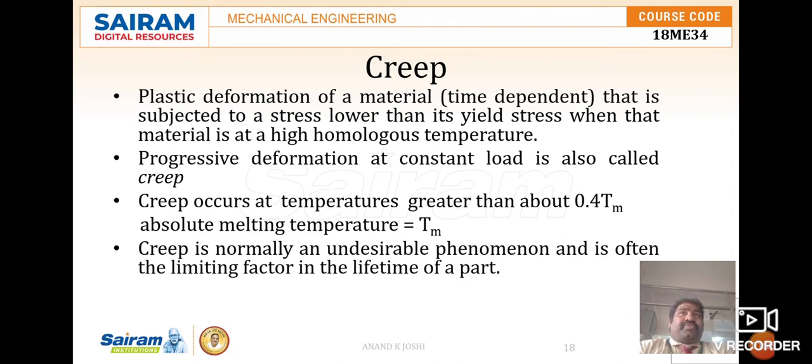Creep normally leads to fracture. It is an undesirable phenomenon, and it is often a limiting factor in the lifetime of a part. Creep can lead to fracture at static stresses much smaller than those which would break the specimen. Hence understanding the behavior of the material at high temperature is beneficial in avoiding failure in these types of materials.